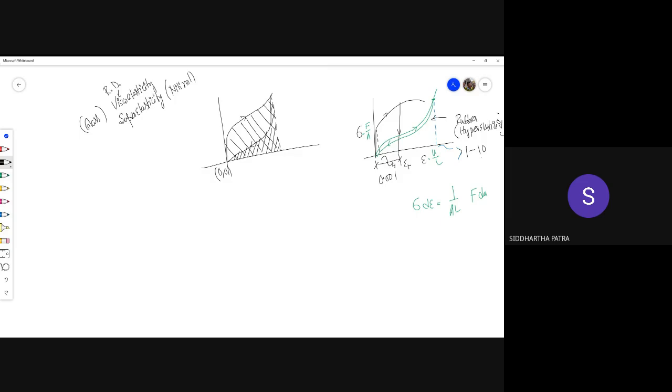So with no further stress, there is no further unloading and no further regaining of the strain. At the end of the process of unloading, you have some permanent strain, in a way permanent. Of course, you can reload in compression and make a full hysteresis cycle and come back to zero strain as always. But the basic idea is the energy is lost in the process, and that energy would be this much.